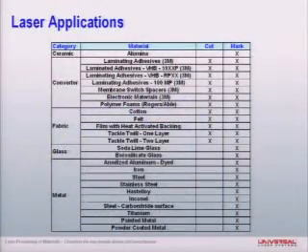One more back. So one of the things that we do in hardware, we make a lot of keyboards and stuff, which are the Mylar switch-based things. So we certainly tried to use the laser to do membrane switch spacers. And one of the problems that we continually run into is that the edge develops a little bit of a lip, and so I've been looking for a good way to avoid that.